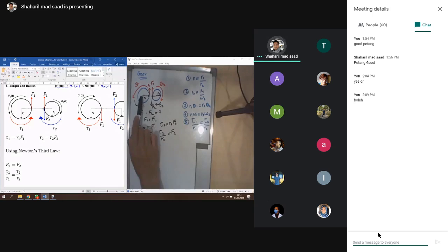Clear. Gear 1 will give some forces F1 here at gear 2, and it also has the same force F1 here, right? So that this gear can rotate anti-clockwise. Okay. So when F1 rotates here and then theta 1 rotates here, you will have the torque T1 here. But this one you will have torque, that means the direction will be opposite, right? If it is not opposite, it will get stuck, right? Okay, so you have here. Now you have the fifth equation.